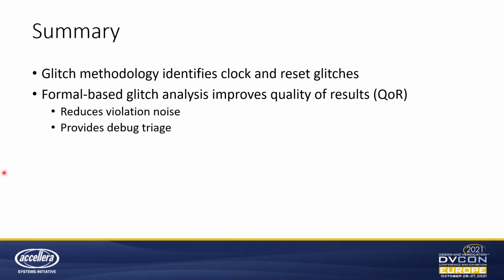The generation of counterexamples under which the glitches would actually propagate makes it obvious that the reported issues are genuine and pose serious threats to our next SOC. Advanced debug techniques that highlight the glitch introduction point help in fixing the glitches efficiently and reduce the verification cycles and respins.